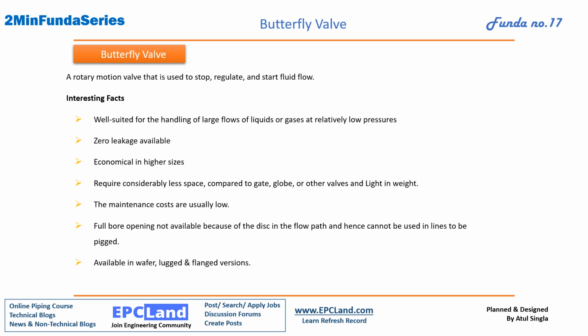Zero leakage available, economical in higher sizes. We'll discuss in detail in the next slide why higher sizes are economical. Requires considerably less space compared to gate valve, globe and other valves, and light in weight. If you see the pictorial view of these valves in the next slide, then you will understand why this takes less space, why these are light in weight, and how these are cheaper as compared to other valves. Maintenance cost is very low.